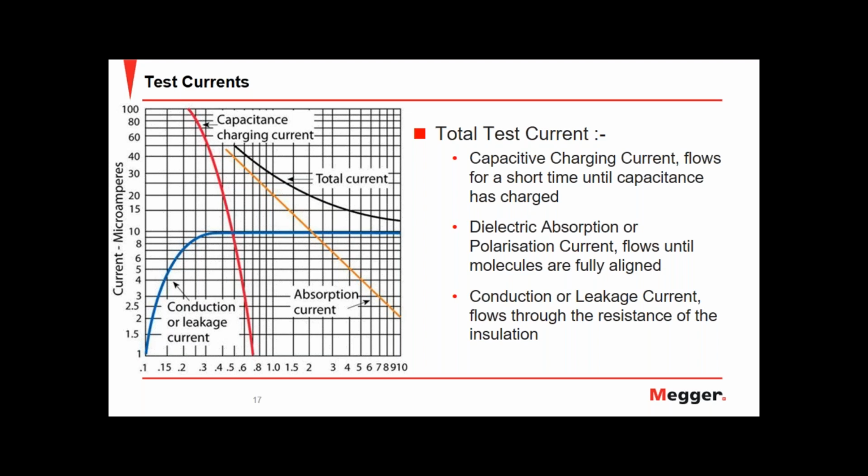That is a common practice in the field, because if you have the cables laying on the ground and the cables are not in good condition, or they don't have good insulation, say you are testing at 10 kilovolts and you have cables that are already deteriorated or are not for that voltage rating, then you're going to have leakage through the insulation of that test lead. So you want to avoid that. Hanging the leads in the air could be a way. Having better leads can be another way.